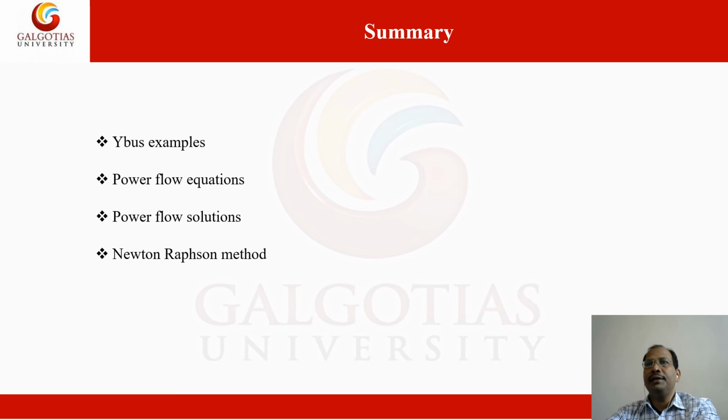Here we already discussed the Y bus. Based on the algorithms, we considered two examples for the calculation of the Y bus. The same algorithm we applied for both examples. Then we discussed the power flow equations, how we calculate Pi and Qi, the active power and reactive power at a particular bus.